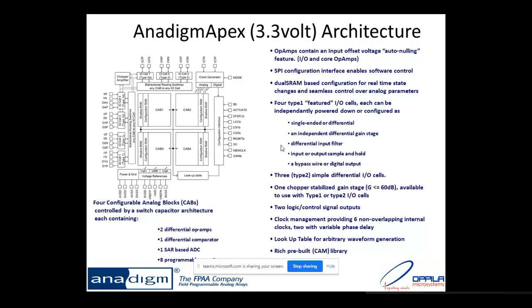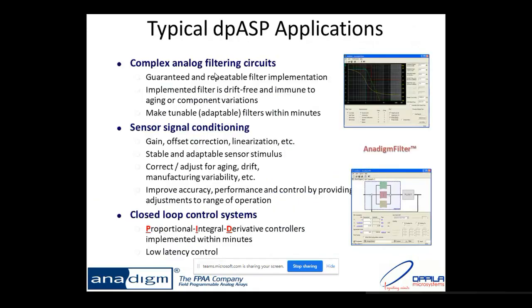Okay, and it is a 3.3 volt architecture. I'm just summarizing it from time to time so you don't forget it. Okay, you will just follow me. And in each FPAA you will be having 7 IO cells. IO cell 1, 2, 3, 4, 5, 6, and 7. Those IO cells can be used to feed the input and take the output from the FPAA as well. Understood? Yes.